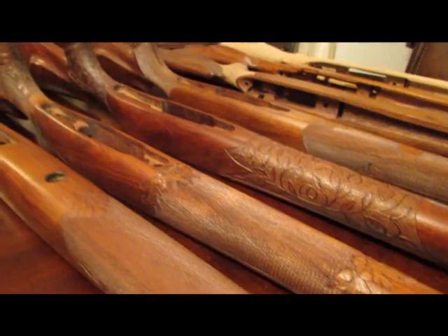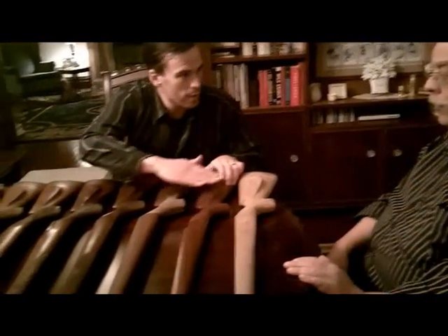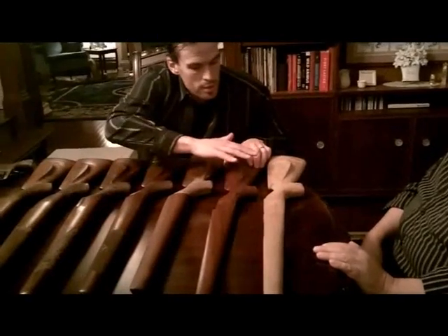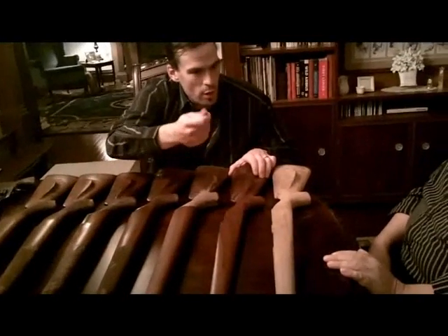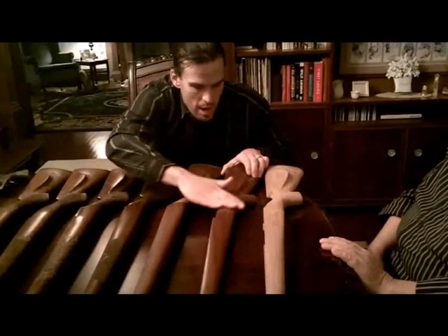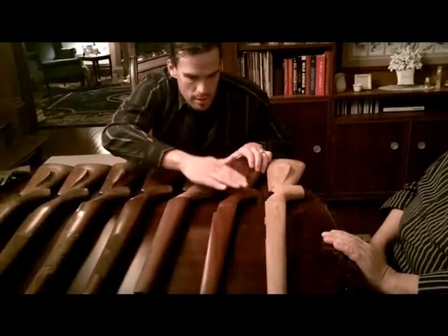So that's one reason why I would recommend free-floating your barrel, because then you eliminate the whole problem of stock warp, especially if you're using a wood stock, unless it's very well sealed, or it's a really, really nice piece of wood. Some of the older wood is actually better because it's got most of its warping done, but it can still be affected by temperature.